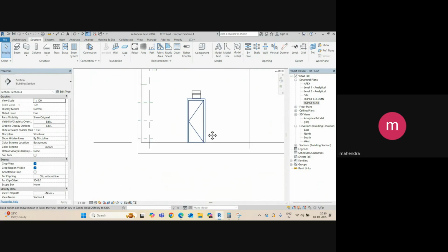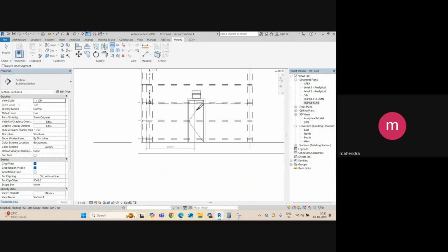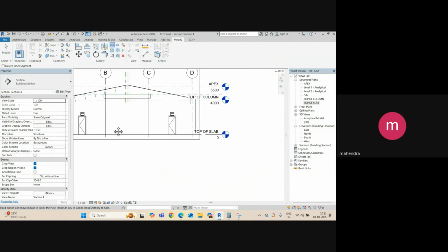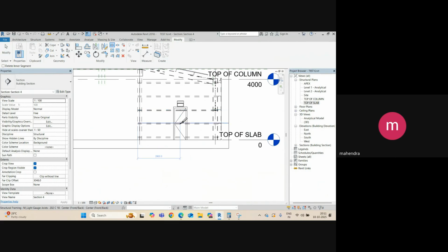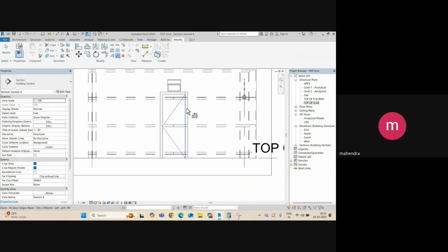So similarly, these purlins you need to cut again. Click this Split Element, then select, then select, then again here select and select. We know how to trim, so use this option. Use your boundary, so select this and just click, click.